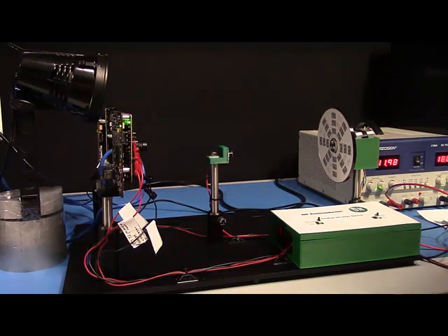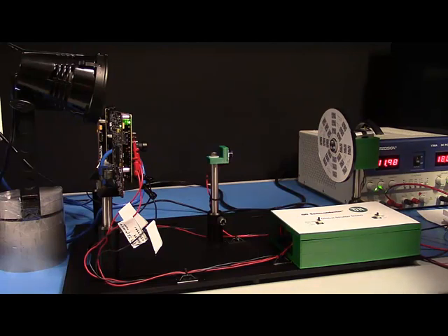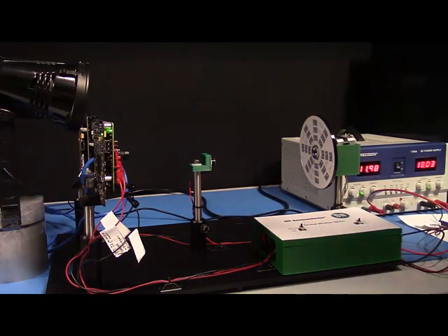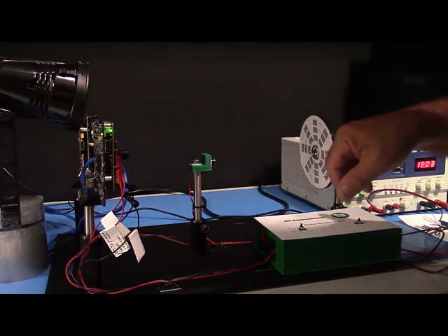We've set up a demo with the AR0144 global shutter sensor from ON Semiconductor, which provides 1280 by 800 resolution and uses the latest 3-micron global shutter pixel. We're comparing it to the AR0140, also from ON Semiconductor, which has the same resolution and uses a 3-micron rolling shutter pixel. The demo is intended to emphasize how in specific use cases where high-speed motion is needed to be captured, the global shutter solution is far superior and can create a crisp, clean image even when the object being captured is moving. Both sensors offer best-in-class image sensing technology.